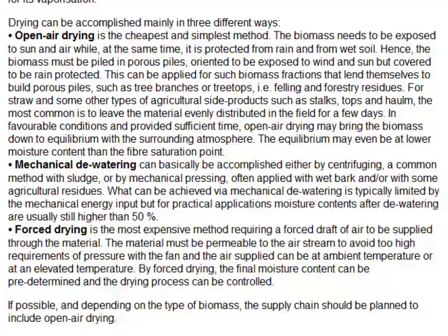With very wet biomass, such as bark from a sawmill, pressing or centrifuging, which are both mechanical dewatering processes, can be applied. Typically, a mechanical dewatering process cannot achieve lower water contents than approximately 50%.